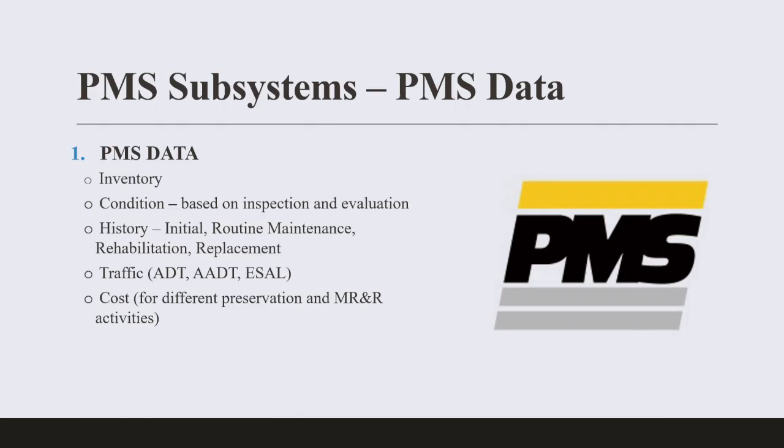Current condition comes after that. Current condition means you have had inspection for every little bit of your road network and every element in your bridge network. Talking about roads, your PCI, pavement condition index, which is function of what? The roughness, IRI, the rutting, and the cracks. This is how we do it in the US. Of course, every country is more than free to develop the criteria that defines the condition, the y-axis.